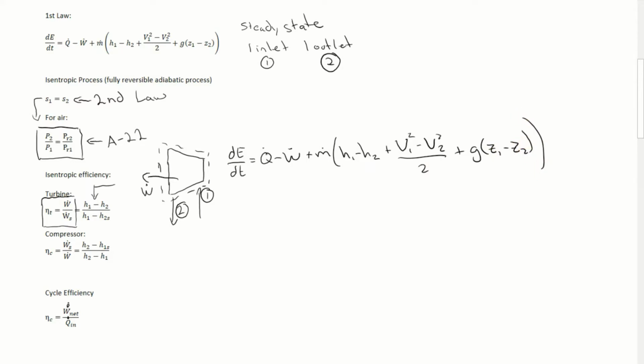So this very long equation. And so in order to find what our power developed is, we need to make a number of simplifications. So we're going to assume steady state. We're going to assume no heat loss, or that this is at least negligible. We're going to assume any changes to velocity and potential energy of the incoming and exiting fluid are negligible.